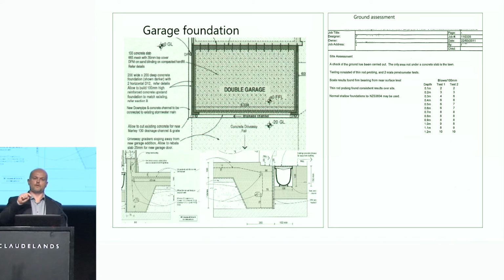And with your construction monitoring, highly, highly recommend just make a note on there saying refer construction monitoring schedule, just in case it doesn't get through to them. Typically, as you know, you walk onto site and they might have your drawings there, but maybe the architect hasn't sent it through or the construction monitoring schedule. So you need to make sure that that's referenced in there.